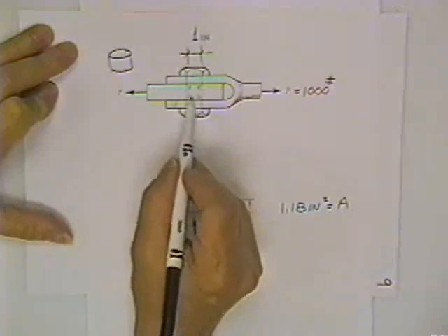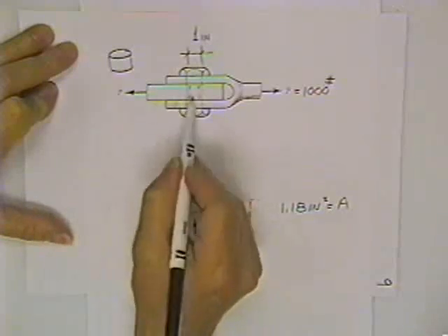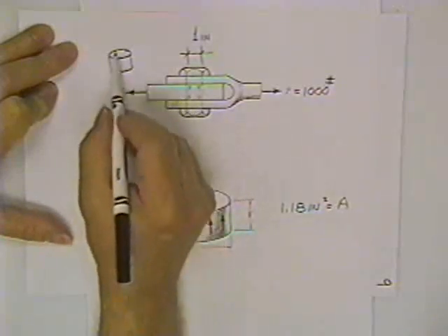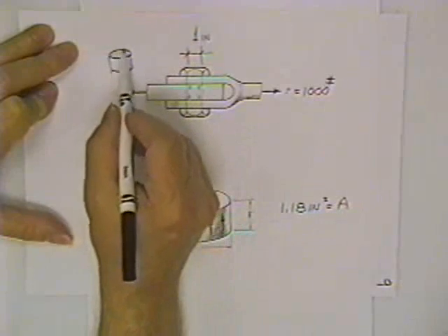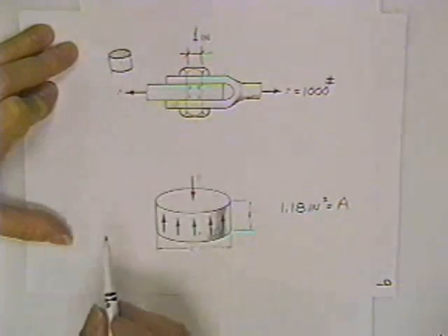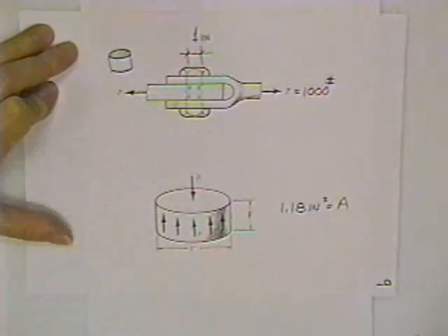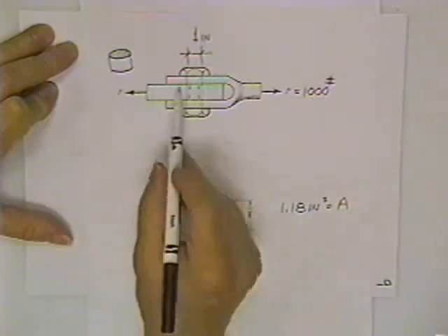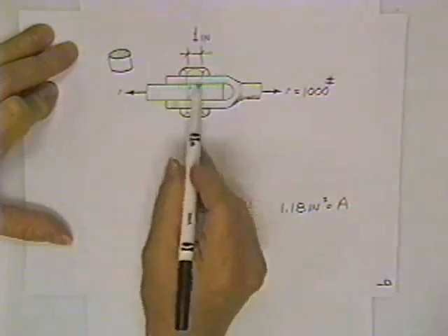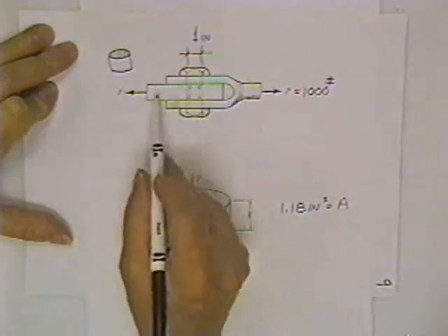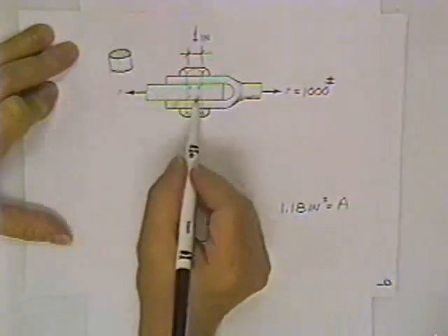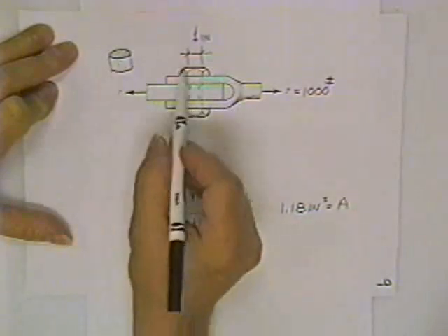And if you take a look at that piece of metal that falls out on the floor once you yank this thing out of here, you'll see it has a nice, new, shiny, scarred up top surface, and it has another one just like it on the bottom. That is the surface area of steel that was originally holding these two pieces together. Therefore, I know the area of a circle.